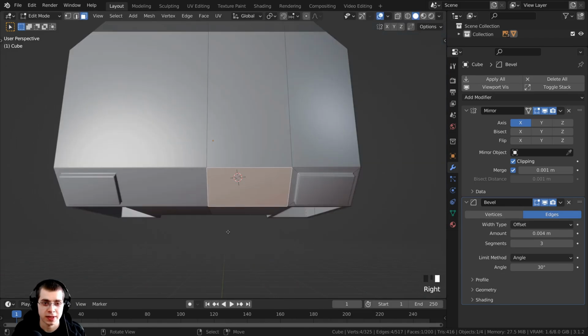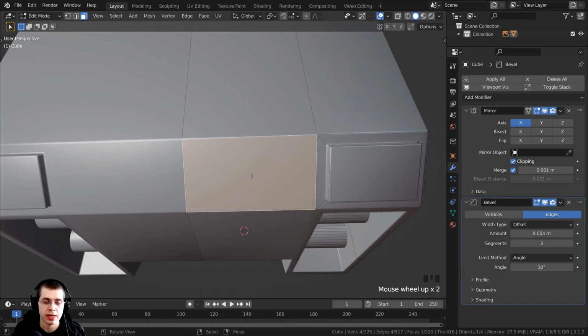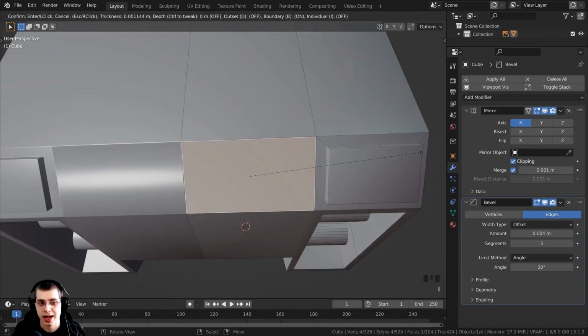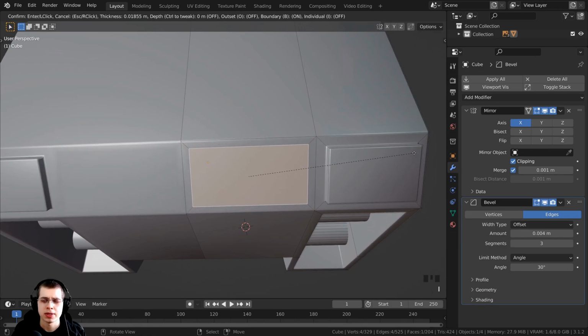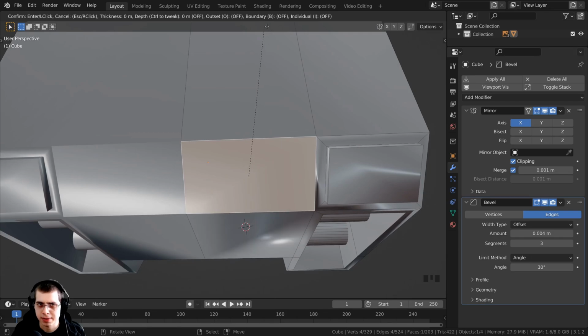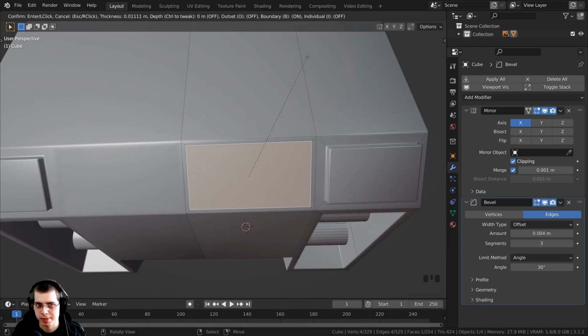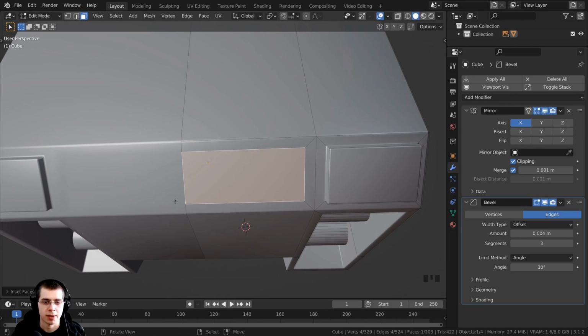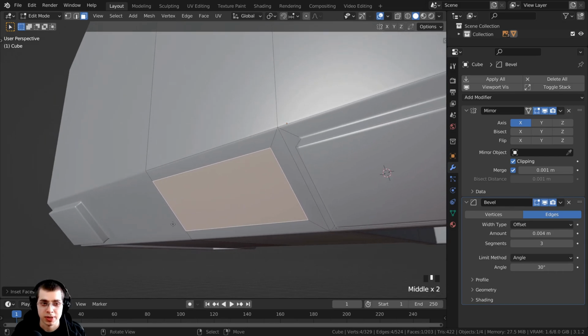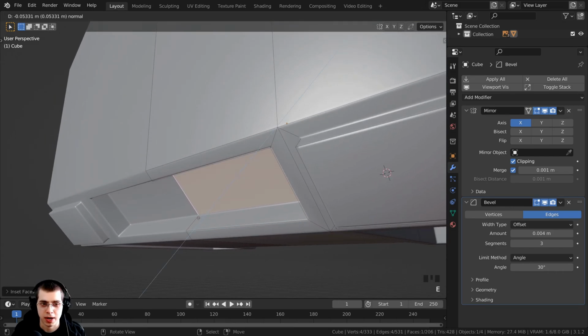And then I'm going to select this face right here, and this face we are going to inset it and then extrude it in. So I'm going to press the I key, and the I key is going to inset this, but you can see it's not actually connecting with the mirror modifier. So after I hit the I key, I can then press the B key. And you can see right up here, it says boundary off. If I press the B key, now it says boundary on. So after you press I, if you press the B key, that is going to toggle between the boundary being on and off. And I want the boundary to be off so that it's connecting with the mirror modifier in the center of the face. And I can just click to place that about there. And then I want to extrude this back in. So I'm going to press E to extrude, and let's extrude this back just like that.